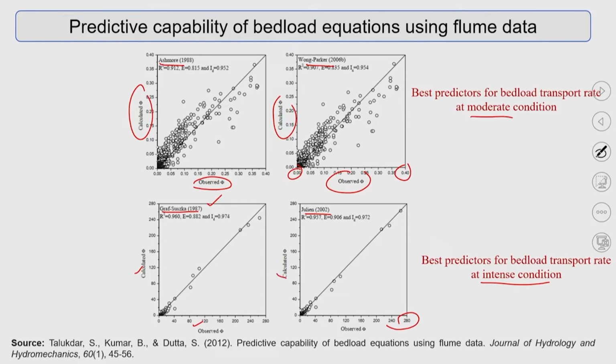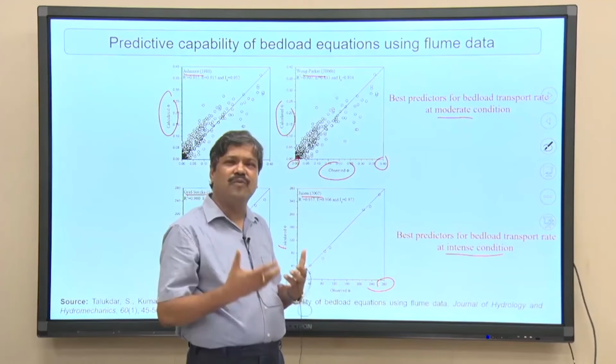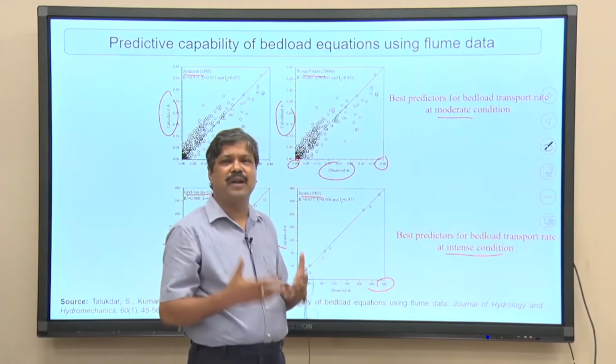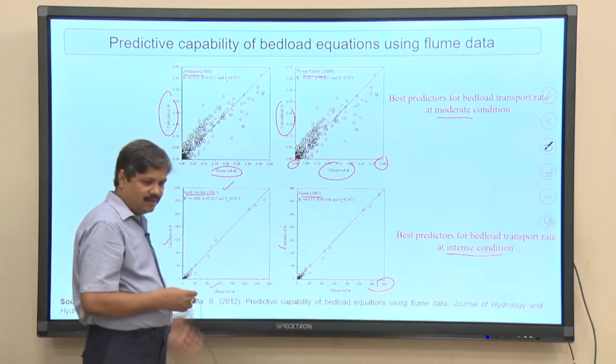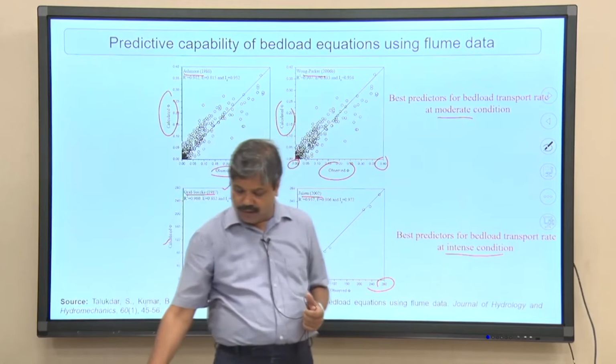To summarize based on this study, instead of using one equation, try to use two or three equations, recalculate the bed loads, and take a judgment on how accurate they are. Most probably, a few measurements can be included in any bed load estimation. You can do a few measurements, or use literature about that river if available, and validate which is the appropriate bed load equation for the particular river reach you are working on. That is my experience when working with river modelling.